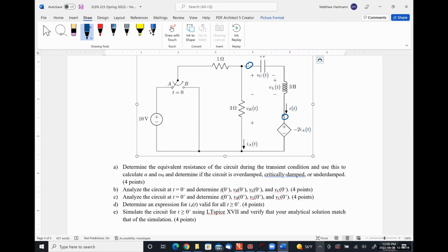So whenever you determine coefficients or constants, it's natural to just use the values you get in your analysis that correspond to the capacitor or the inductor. But if you're looking for the resistor quantities, the problem is that the current-voltage relationship for a resistor does not have a derivative-based relationship. So you cannot use it to set up your equations to determine your response. You can only figure out what's going on with the resistor once you know what's going on with the capacitor and/or the inductor.